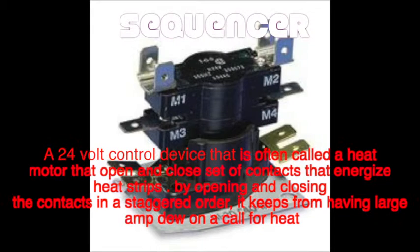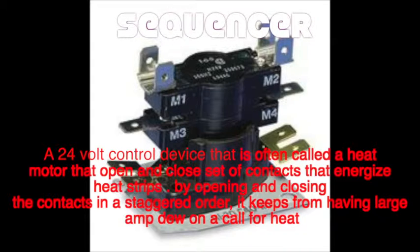Sequencer: a 24-volt control device, often called a heat motor, that opens and closes a set of contacts that energize heat strips by opening and closing contacts in a staggered order. It keeps from having a large amp draw on the call for heat, so that way your circuit breaker won't be in defeat. That's a sequencer. Check it.